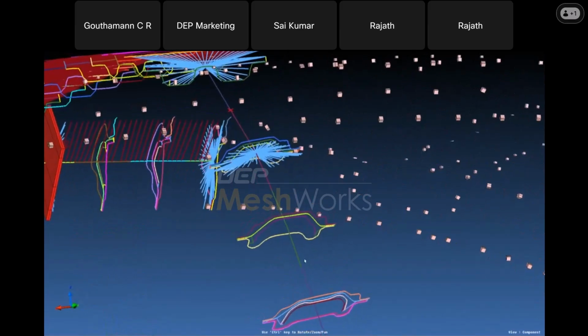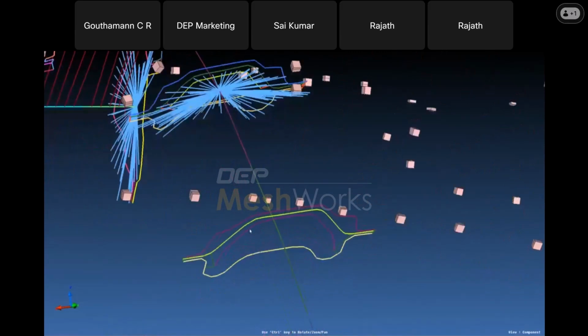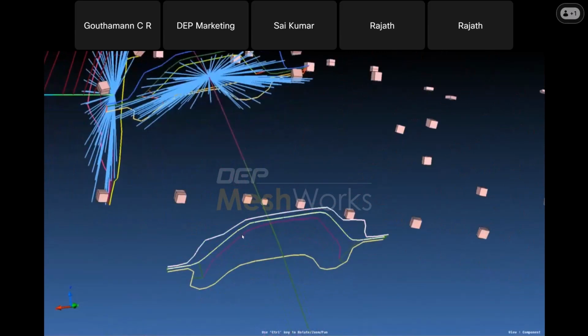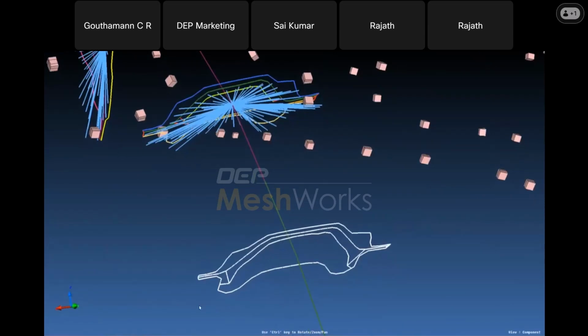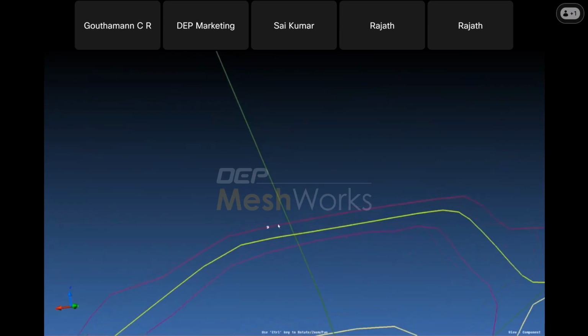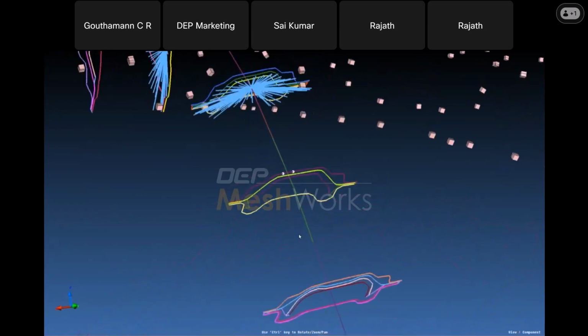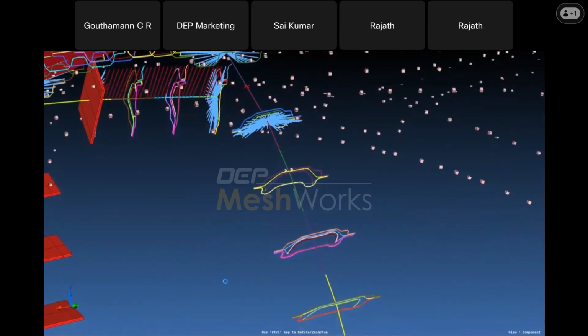All we have to do is select the 1D components, and select the 2 nodes along the width direction and say preview block. Should take about half a minute.